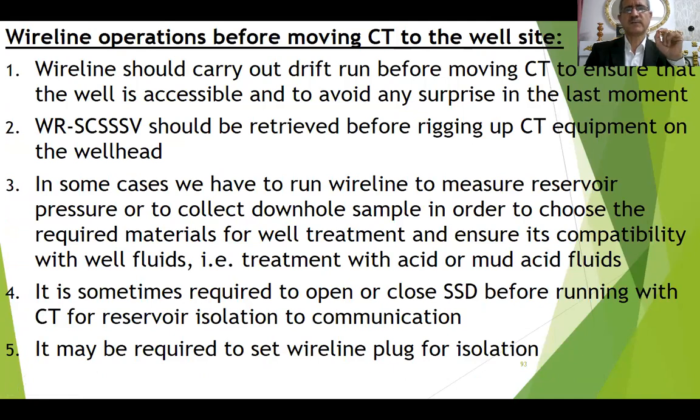While operations before moving coil tubing to the well site, what can we do? We can do drift run, pull well and retrieve subsurface safety valve. In some cases, we have to run wireline and measure the reservoir pressure and collect data for killing program. It is sometimes required to open and close SSD in horizontal and highly deviated wells. Also, it may be required to set wireline plug to isolate the formation.